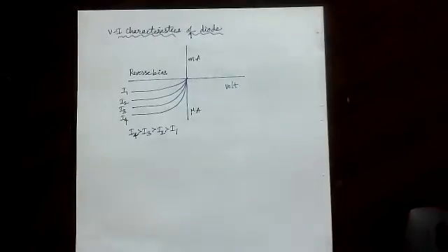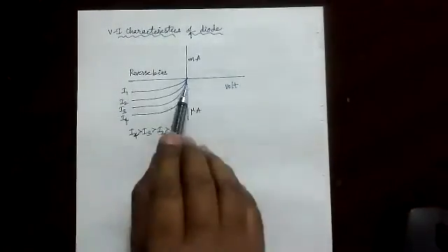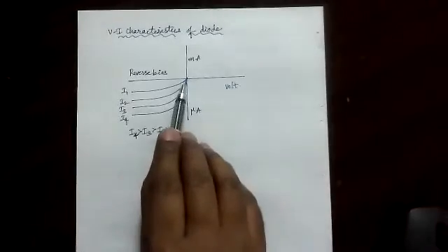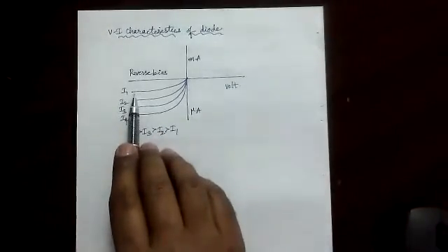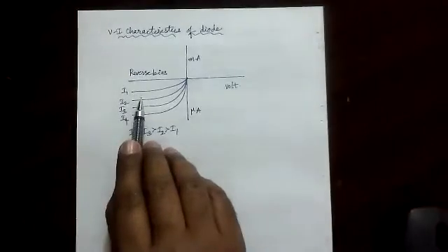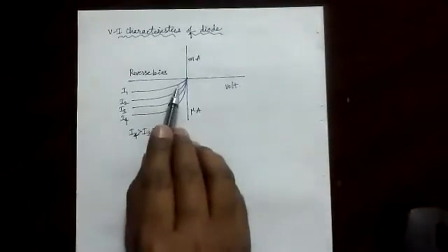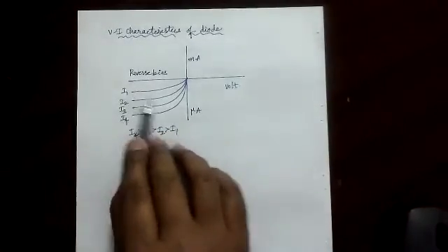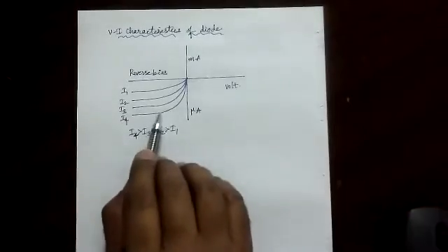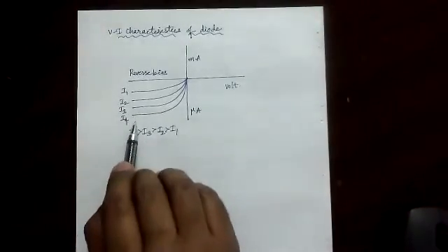So what is happening here? This works in the reverse bias. See, as the reverse bias voltage is increasing, we can think about the intensity. We are giving one particular intensity. So think that we are giving one intensity of light. Then as the voltage is increasing, the current is remaining constant. See here, after that the current remains constant. Like this for less intensity. For more intensity, you can see more is the current flowing through that one. Is it clear? More is the intensity, more current flows.